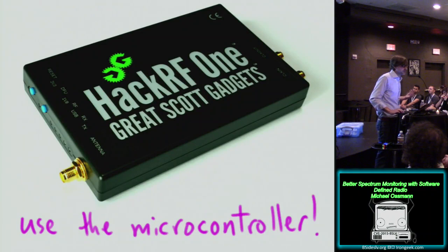So I'm using the microcontroller in the HackRF, and there are other software-defined radio platforms where we should be able to do this too. Any SDR platform where you have control of the tuning from the embedded device itself, as opposed to a control interface like USB. Generally speaking, I think HackRF's the lowest cost device, at least it's the lowest cost transceiver that gives us that capability. Unfortunately, I don't think the Realtek dongles have a way to give us that capability, although it would be cool if somebody figured out a way to hack that in.